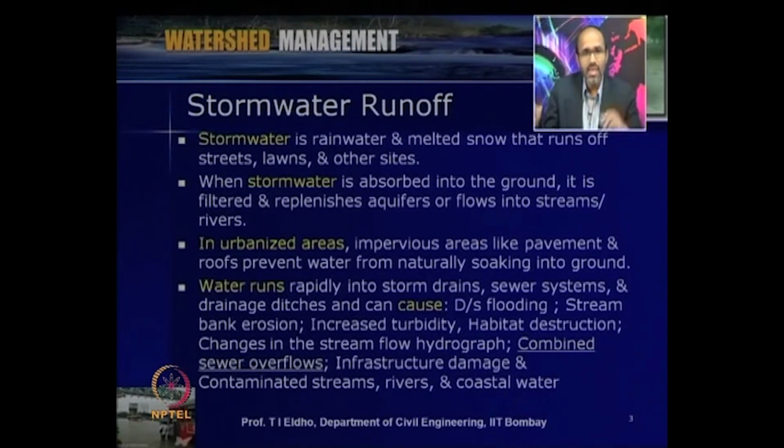So then there can be increased turbidity. Another issue can be increased turbidity. And then habitat destruction, and changes in the stream flow hydrograph. That means especially in the urban areas, due to the shorter time of concentration, the time to peak will be less, and then the peak also increases. So that way there will be changes in the stream flow hydrographs.